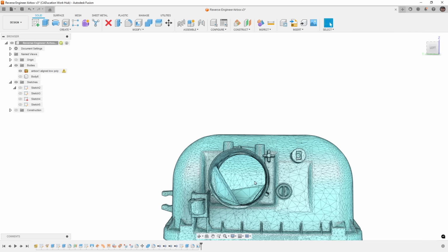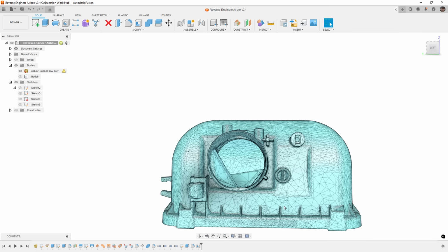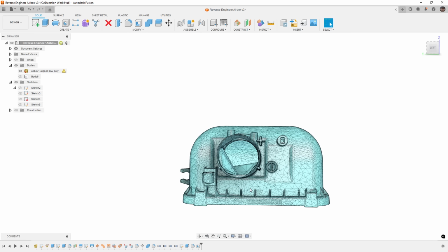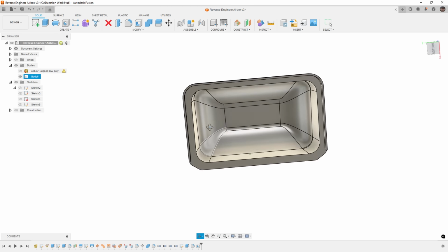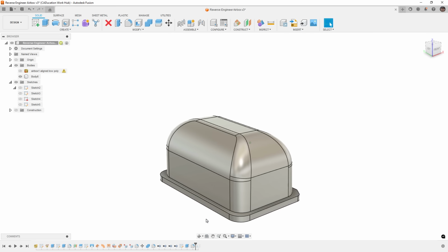So it is consistent wall thickness. And then all these little pieces that are on the outside, things like this intake or this inlet, all the ribs, all the attachment features, all of that stuff is going to happen after we have our thin wall part. Because you don't want to do a shell when you've got things like these bosses here. So that's something that you would just do after the fact. But that's going to be the basic approach that we have to create that general shape. So I'm going to roll back before the shell, knowing that we can go back to it later.